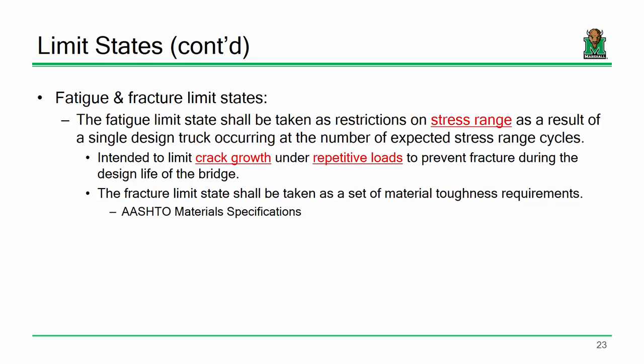Fatigue and fracture. This is a really unique one, especially for steel. One of the quirky things about material behavior is the concept of fatigue, and it's a really important one in the world of bridge engineering, because fatigue is a phenomenon related to any element subjected to cyclic loading: loaded, unloaded, loaded, unloaded, which happens to bridges all the time. From a material standpoint, we'll get into this a little later, you might have a steel with a yield stress of 50 KSI, but you look at a fatigue detail and it can't go above 12 KSI.